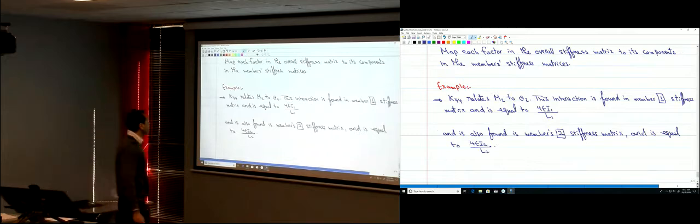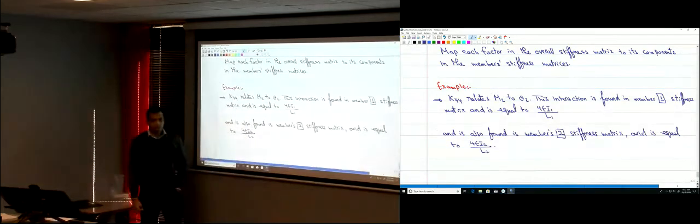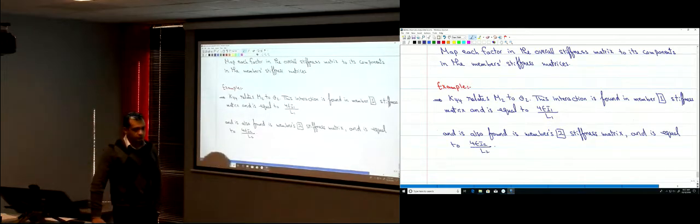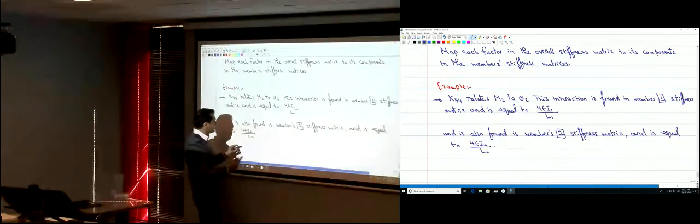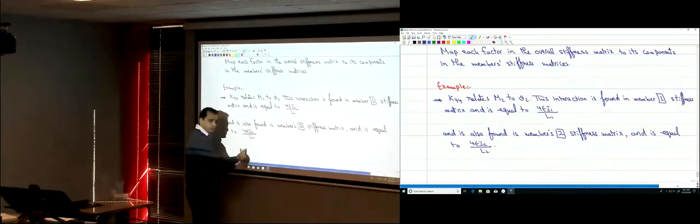So to build K44, do you use this one or this one? Are the lengths equal? They are not equal, right? The formula looks the same, 4EI divided by L, but this is the length and moment of inertia of member 1, and this is the length and moment of inertia of member 2.